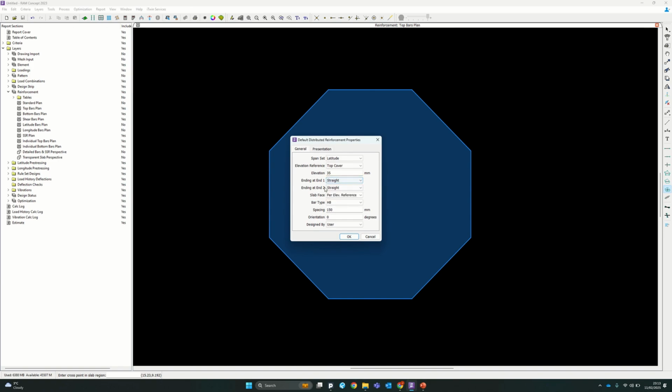This is very useful to know. If you don't correctly anchor the bars within your slab, i.e. at the corners, putting 90-degree hooks in, that sort of thing, which in this case, if it was a pile cap or something, you would place 90-degree hooks in so that it can lap onto the bottom reinforcement and anchor itself in.